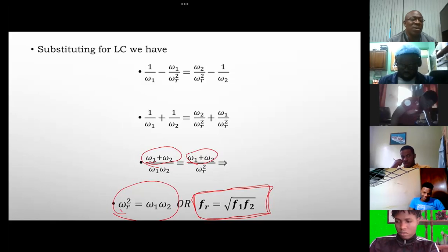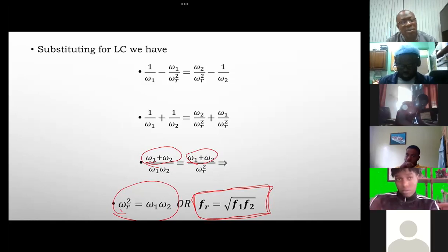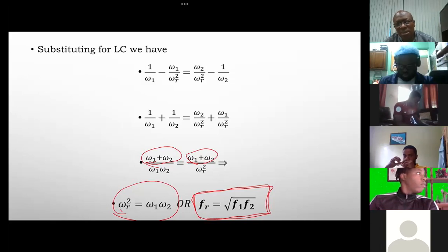you have that bandwidth equal FR over Q, you have a formula for Q, you have a formula for, well, you know the relationship at resonance in terms of the current and the impedance and the phase angle and the power, right? We have gone through all of that, okay? And having said all of that, I can now pause and say to you, we have nothing further to say regarding series resonance. You have done everything.